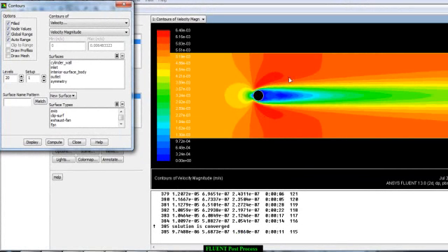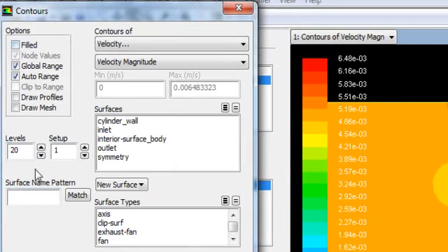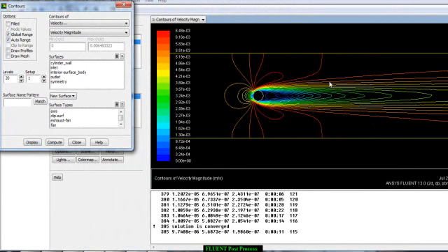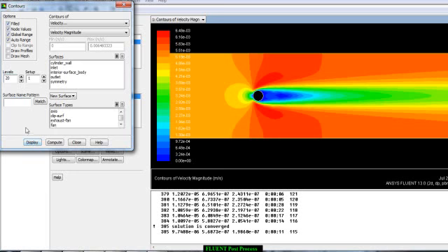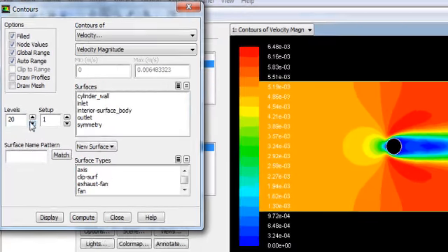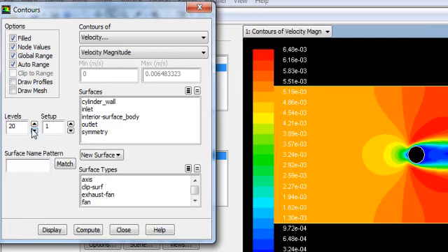You can see discrete contour lines, and here you have the field option. So if you uncheck this field option, you will only see the lines. So if you want to see only the contour lines, you can see that. If you want to see the contour filled with color, you can also see that. If you want to smooth this color, you can change it to the level 100%. One thing you need to understand is that this level is just the color level. It will not affect your results or anything. It's just a presentation option, how you want to present.